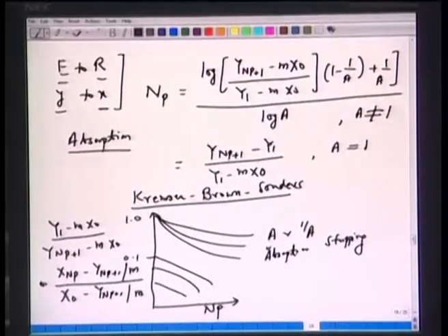All right. So, this was a very special case where we assume that the equilibrium curve is a straight line. So, in that case one does not have to make a material balance for every stage, 10 stages, 20 stages. We can use these expressions directly.